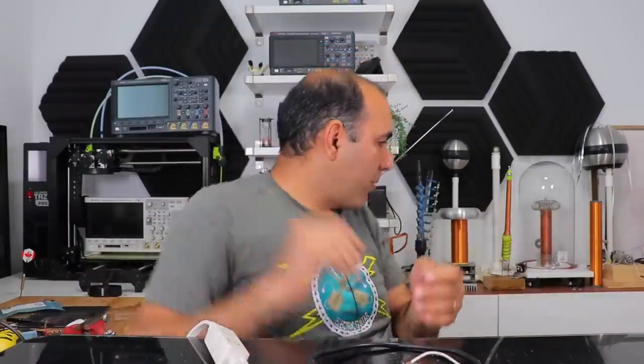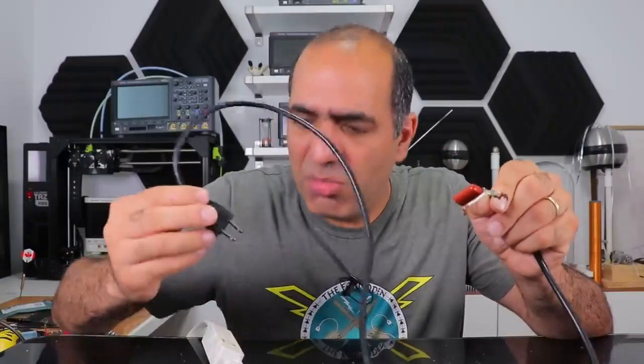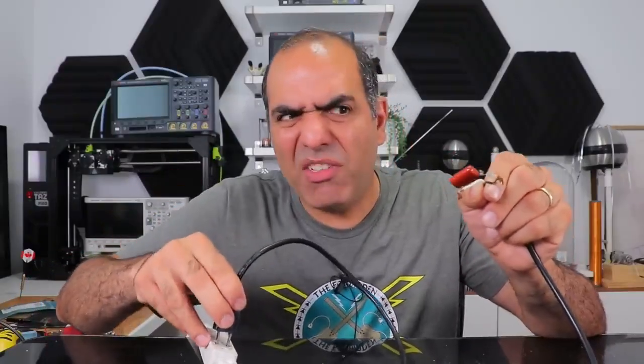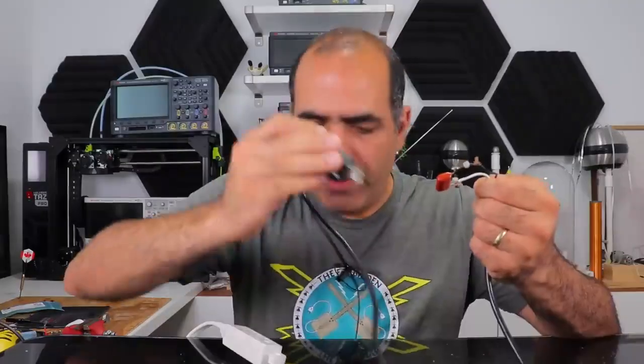Let me see if I have a capacitor that can handle 120 volts. Hey, I found a ceramic 1 microfarad 250 volt capacitor that should limit the current of the LED to around 32 milliamps, which is a bit over the... And the LED is already dead. Next LED. Here, a new LED.